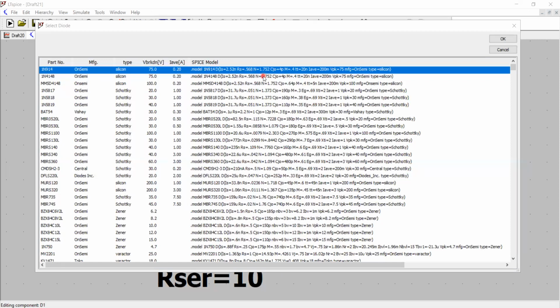Then N equal to some parameter linked to the diode, 1.75. That's the CJO, the junction capacitance of the PN junction. When you connect P-type semiconductor with the N-type semiconductor, you have the depletion region, and that gives rise to the capacitance of 4 picofarad here in this case. And the other parameters you can verify yourself.